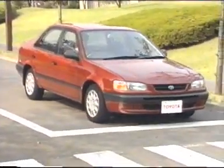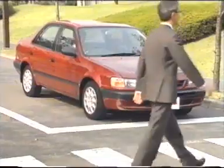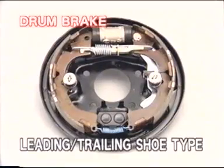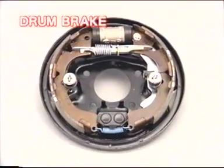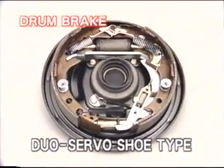The boosted and adjusted brake force is eventually transmitted to the drum and disc brakes. Motion energy is converted to thermal energy and the vehicle stops. Types of drum brakes depend on shoe installation or number of cylinders. For example, the leading trailing shoe type, 2 leading shoe type, and duo servo shoe type.